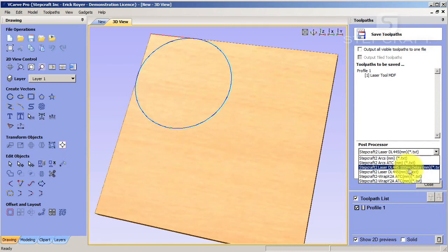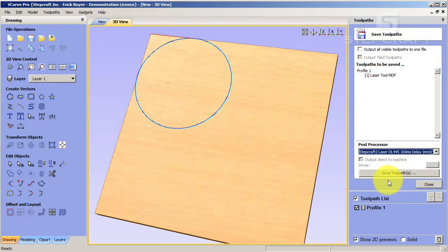These post processors that have 100 milliseconds delay are made for working with paper. Sometimes the laser doesn't like the white color, so to work with the laser you need to use not too white colors when you're trying to cut or engrave. We made this post processor to work with dot lines. The normal post processor doesn't make the dot lines very well because the laser has a small delay when it turns on and turns off.